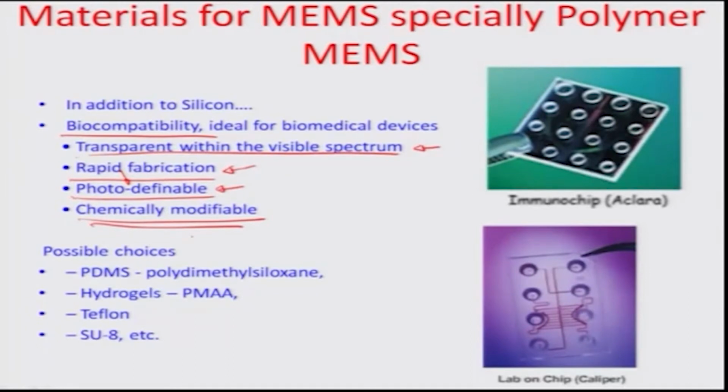and out of all these different criteria for generating an alternate material for doing microstructuring or MEMS work, the possible choices which emerge are PDMS, polydimethylsiloxane, again a very good polymer which comes in two phases, but it reacts and bonds as an epoxy and makes a rubbery membrane, and you can microstructure this membrane by making it through a micromolding process.